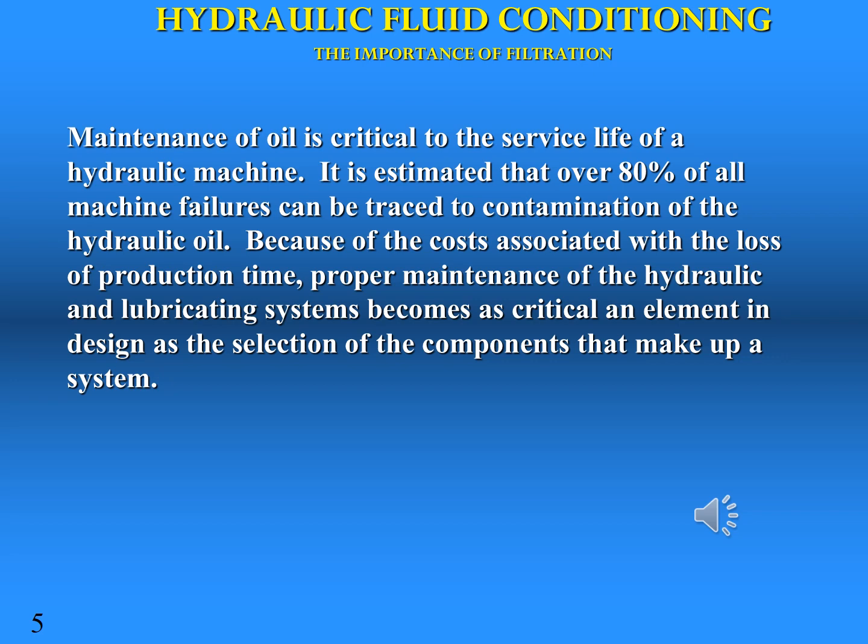Any failure of the pump requires that the system be flushed, valves removed from their mounting locations, and compressed air used to remove tiny particles. 80% of all machine failures, regardless of type, can be attributed to contaminated fluid.